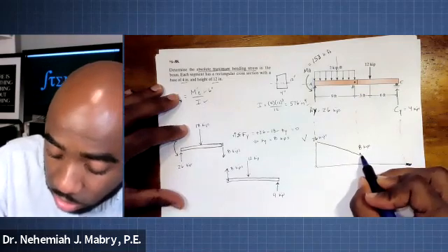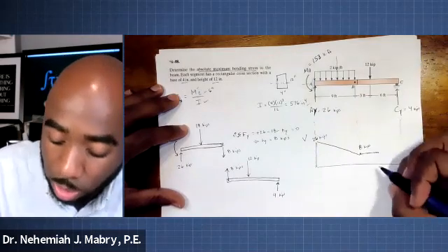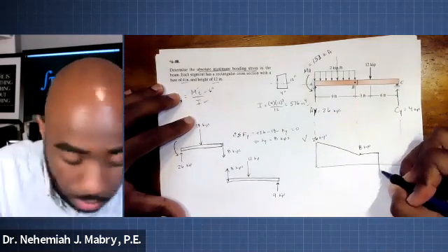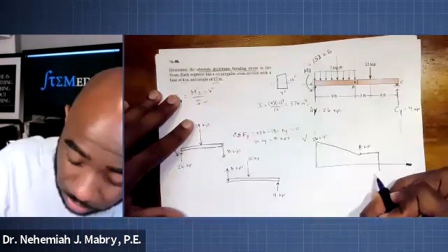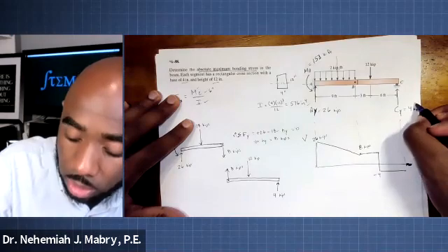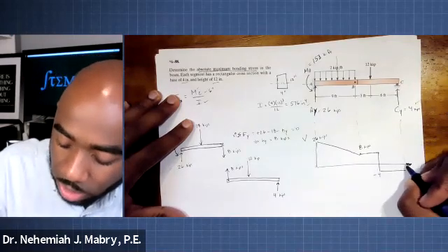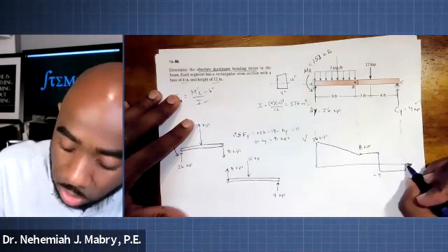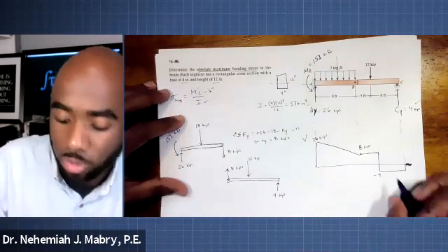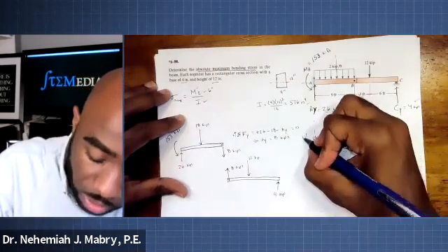This is going to stay consistent over here, moving over. And then it's going to go down another 12 kips, so from 8 kips to negative 4. Going to stay at 4. And this is how you know you're correct, because the reaction right there at the end, the Cy, is also 4 kips. All right, so there is our shear diagram. That's our shear diagram.